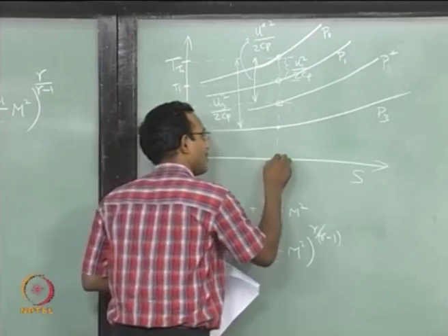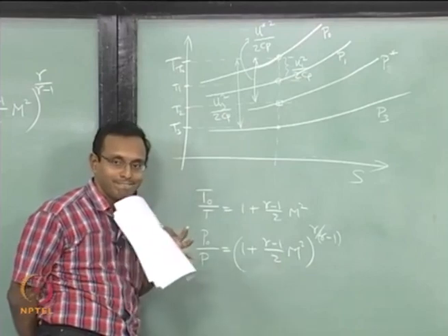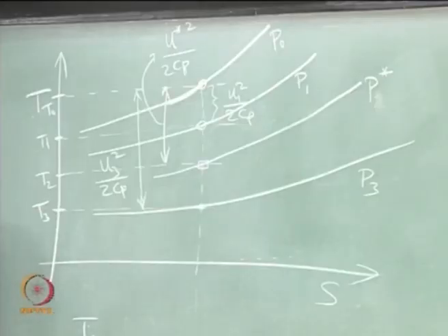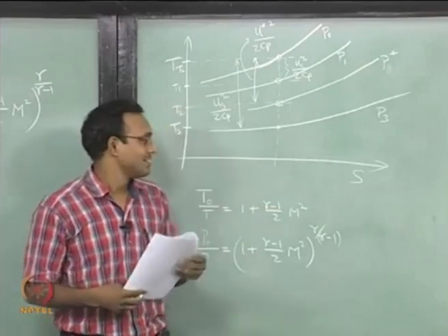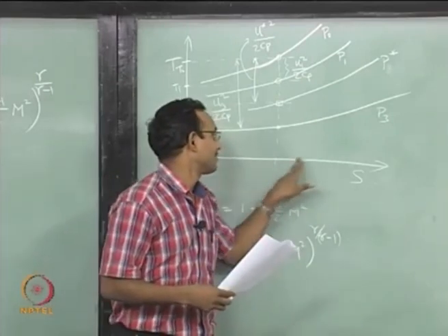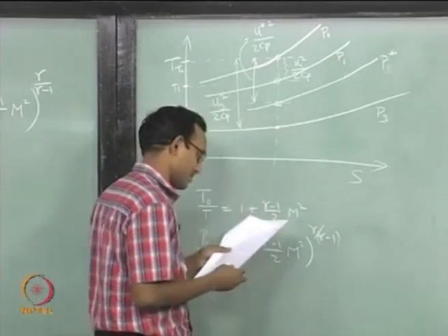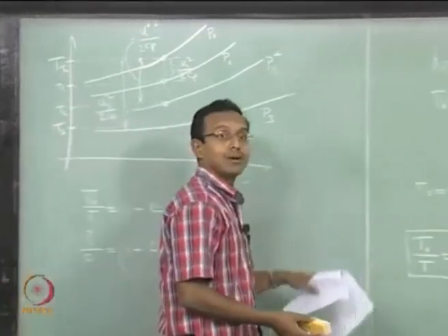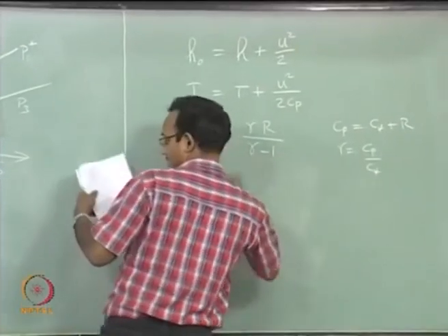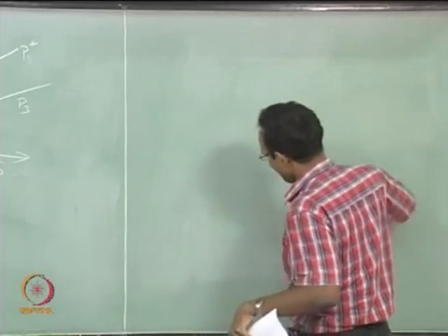So, that is the connection you have to get. And if I draw a pressure curve through that, what will that pressure be? That will again be 0. It is an exponential curve with 0 on the top. So, it will just be a flat line. It will be going along the axis. So, we will not talk about that kind of special cases right now. We will never have Mach number going to infinity happening in our gas dynamics. We will keep it high, but not going to infinity. Now, we will go look at this whole thing in the other plot, PV diagram. Anything I do in TS diagram, you should be expecting to go look at in PV diagram.